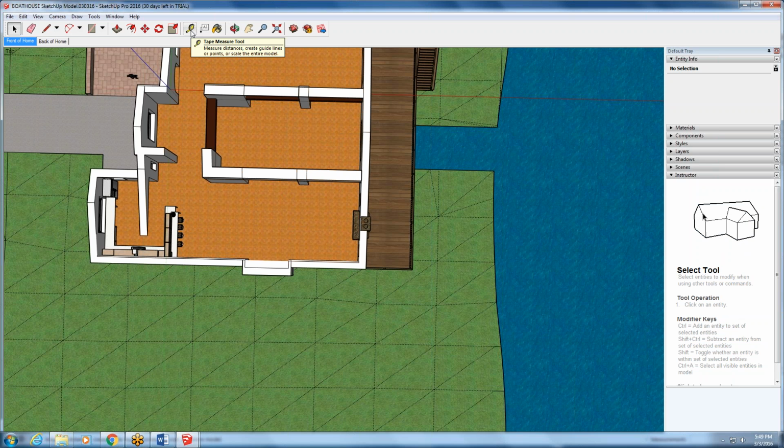Here's a tape measure. This is scale. It's very similar to the AutoCAD symbol. Rotate is also similar. Move. Offset looks a little bit different, but the word would help you figure out what that tool does. And push-pull, because this is a three-dimensional only tool, is something that's not in CAD and you have to learn for SketchUp. We have rectangle, arc, other shapes available, circle, polygon, different types of arcs, just like in AutoCAD, although we focused on the 2-point arc. Same in here, we're going to focus on the 2-point arc.